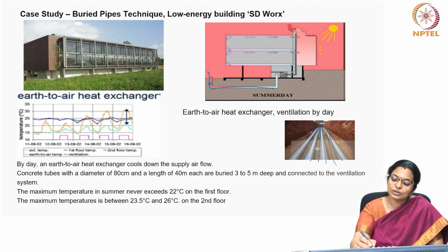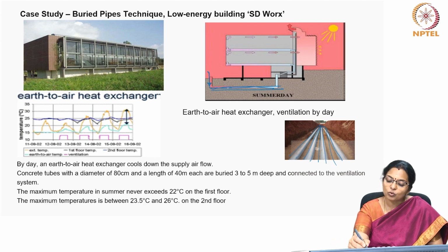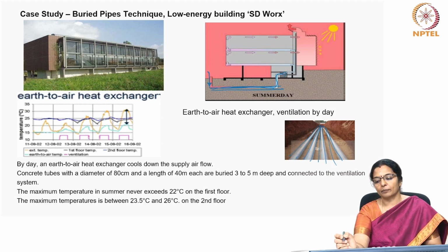Air is pumped through this pipe, and because of the lower temperature of earth in the subsoil, which is actually the average of that place, that cools the air which passes through the pipe, and therefore cool air enters the building.